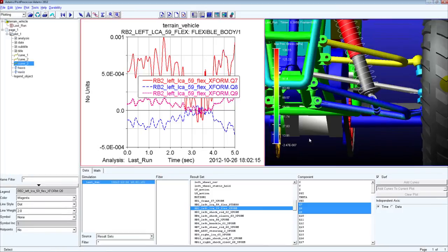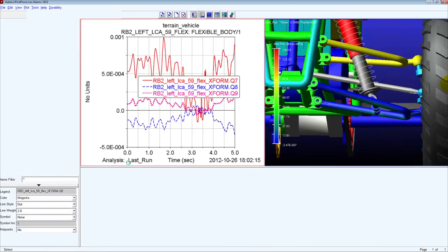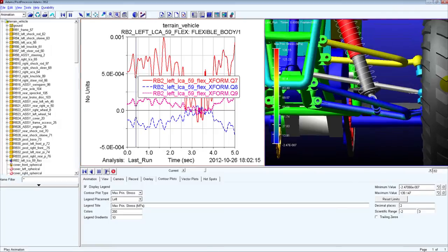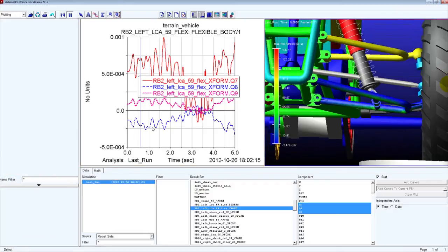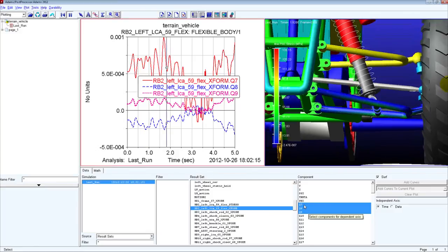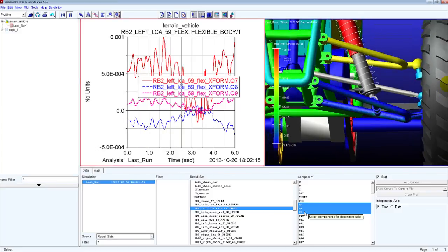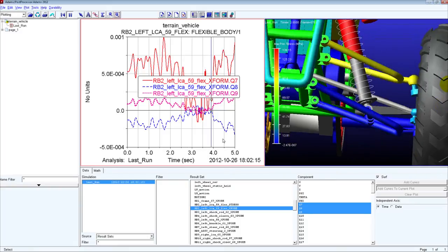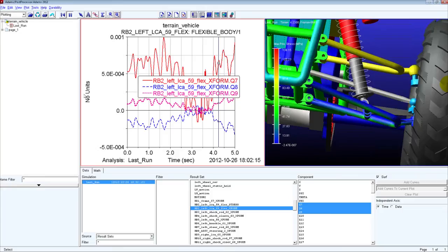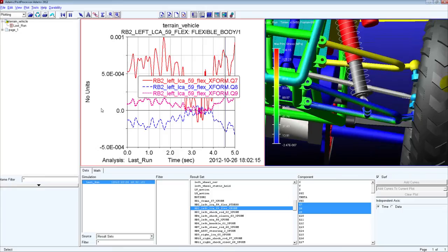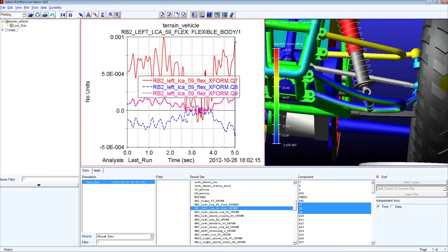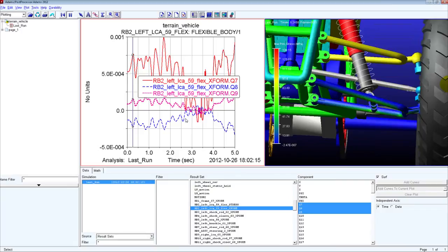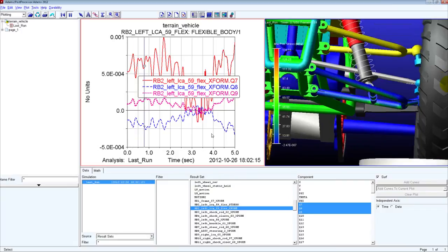Interestingly here, I'm going to animate this thing again. What we're showing here on the plot is we have selected 3 modal participations for modes 7, 8, and 9, just to show how the modal participation functions are really time histories. So they don't have units; they just multiply the modal stresses or the modal deformation to basically identify how much each mode is participating at each moment in time.